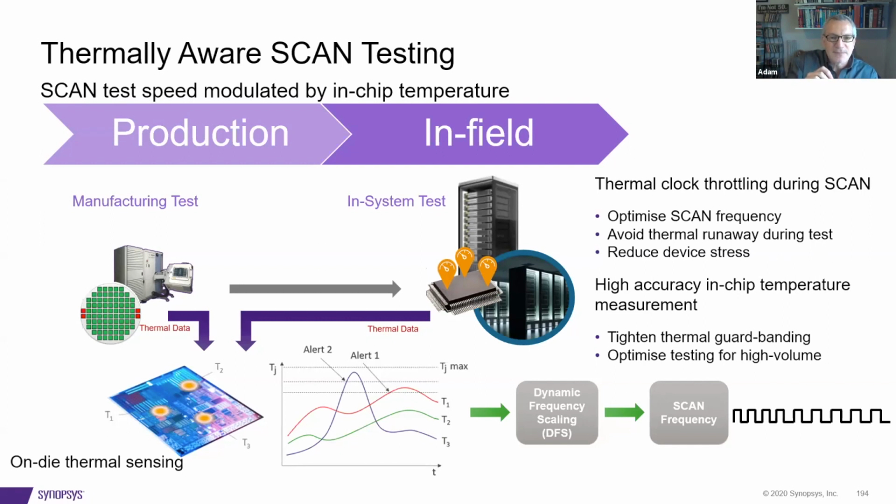But if there is a capture operation, then yeah, new data is loaded into those flip-flops, and there is switching activity on the way out as well. But all that's calculated in the ATPG algorithms that are used today.